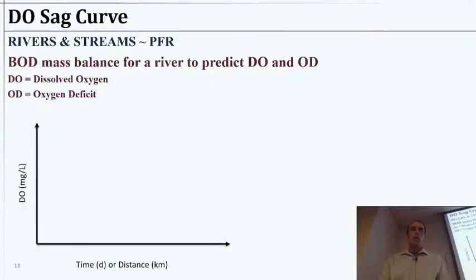Okay. So let's then consider what happens to our dissolved oxygen. Well, DO, we probably have some saturation value. So it's worth considering what our saturation value is. This will depend a little bit on the stream chemistry and a lot on the stream temperature.